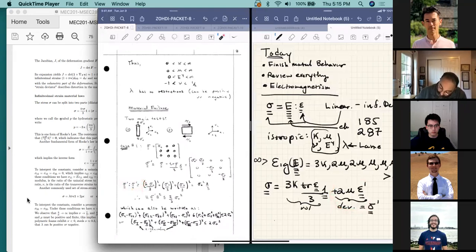And the deviatoric stress's magnitude, we get that by taking the inner product of the stress with itself and then taking the square root. And if we do that, we find out that this is equal to 2/3 sigma 0 squared, raised to the 1/2 power. And that parameter then is the failure parameter that is usually considered to be the yield stress in theories of plasticity.